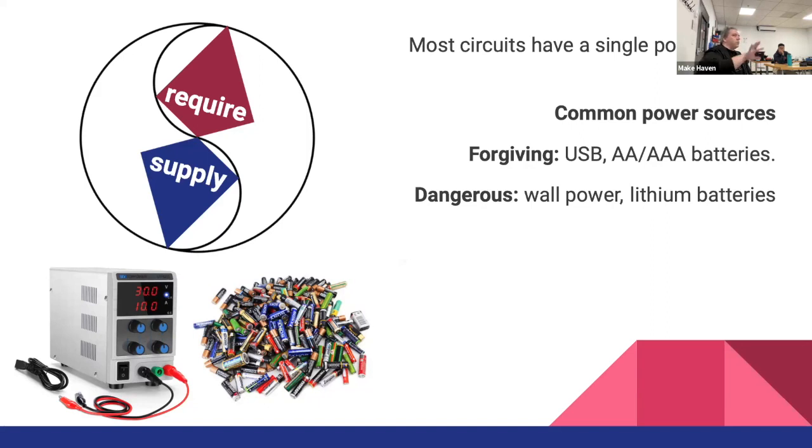The only warning I would give about using USB to power your electronics is that it is possible to damage or destroy USB ports on laptops if you connect bad circuits to them. USB is a great way to get power, but when you're first prototyping a thing, I suggest not powering it from the computer if you can help it. My son's laptop is constantly screaming about overcurrent on its USB ports because he's created short circuits on his Arduinos.